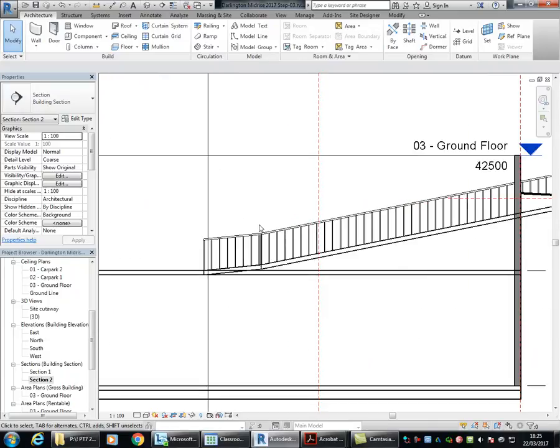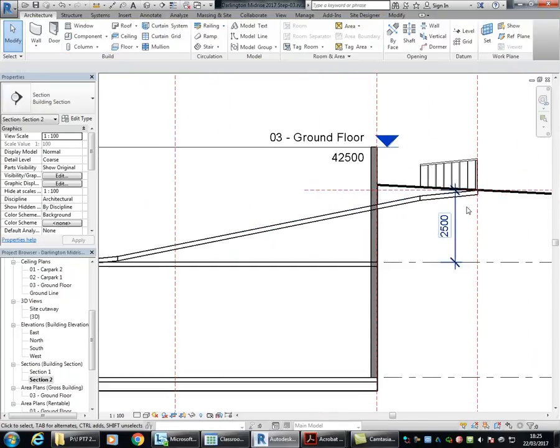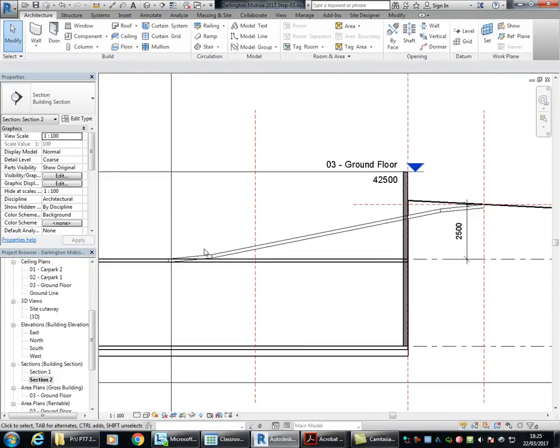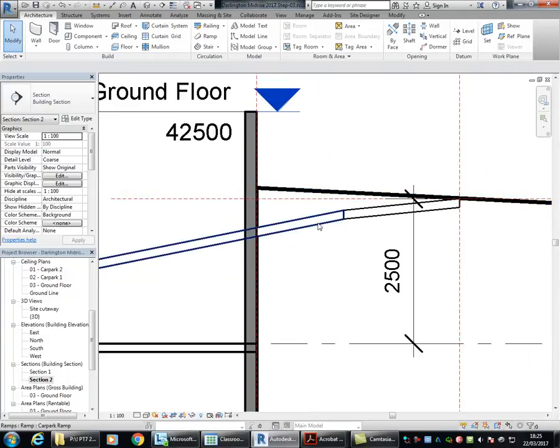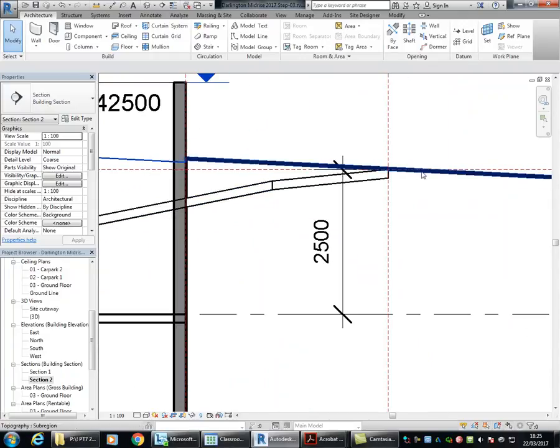The railings aren't necessary, so you can delete those. You'll probably have a concrete balustrade in the areas where you don't have walls, but that can be made with a different tool. If you need to do plain flat railings, whether they're concrete or glass or brick, it's often better to make them with a different tool rather than the railing tool. So the wall tool or just modelling place is better than railings. So yeah, so we've got the ground there still covering up that